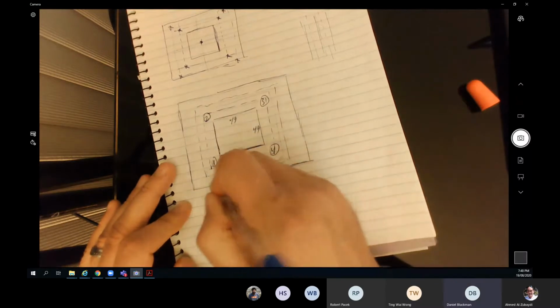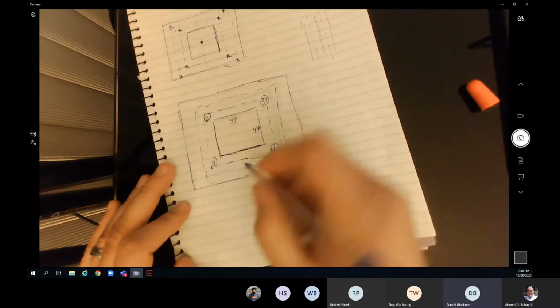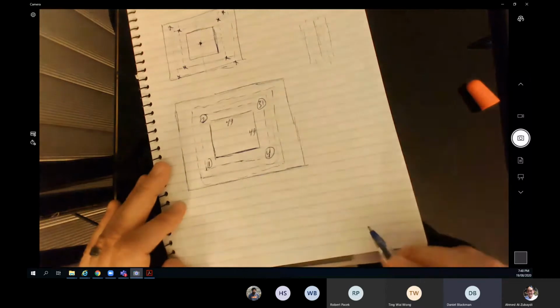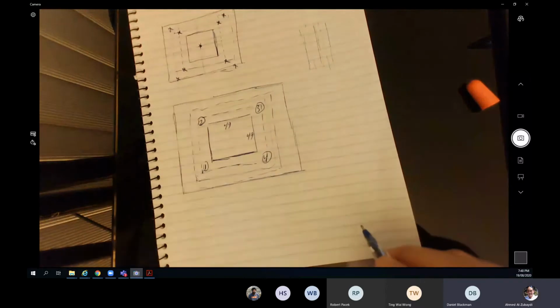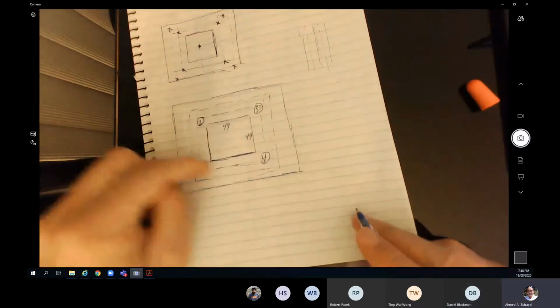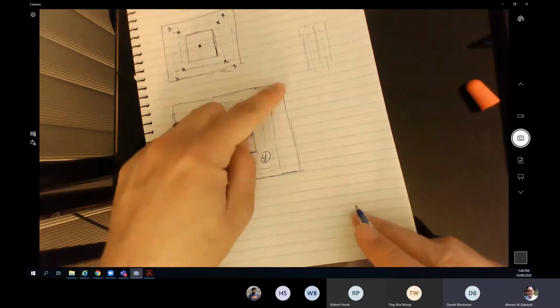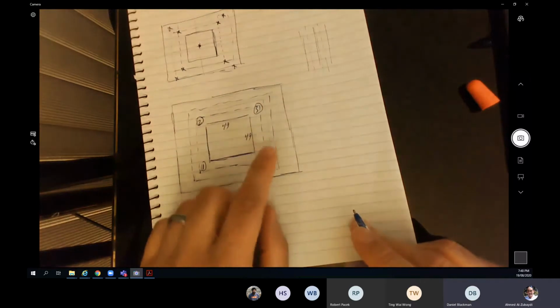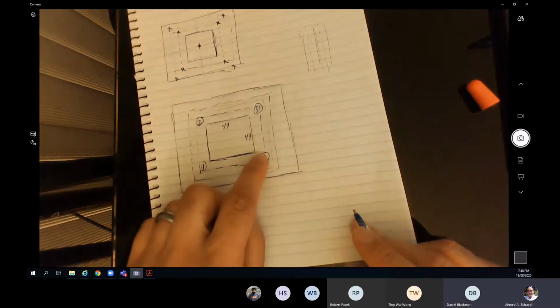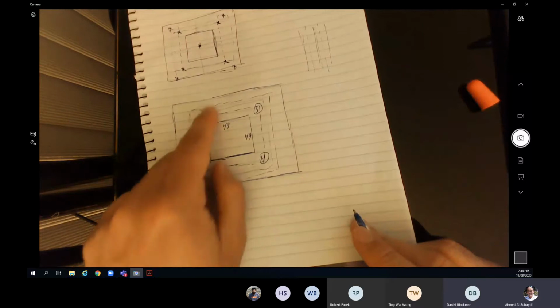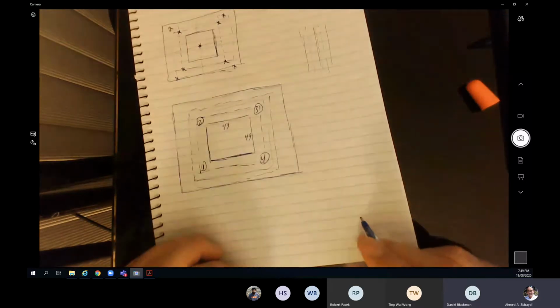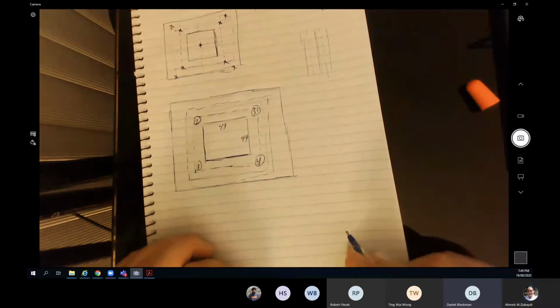Why did you cut the center square shape out first rather than starting at the outside and moving in? Okay, this will make it much easier for you to start from the inside to the outside when you do the manual G coding. So you're not going to start at the end and cut the square by mistake. Also, the machine might do the operation the other way, from the outside to the inside. It can. Yeah, it can.